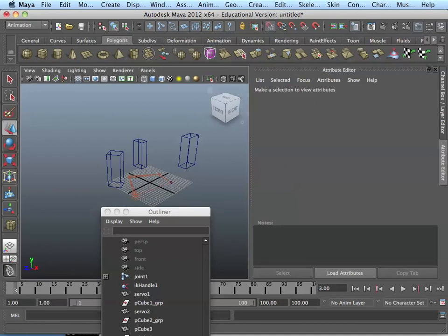The one thing you do have to remember, though, is to get things to work correctly, you have to go from the connection of the ground of the external into the ground on one of the ground pins on the board, because they have to share the ground to be able to communicate correctly. That works for any of them.